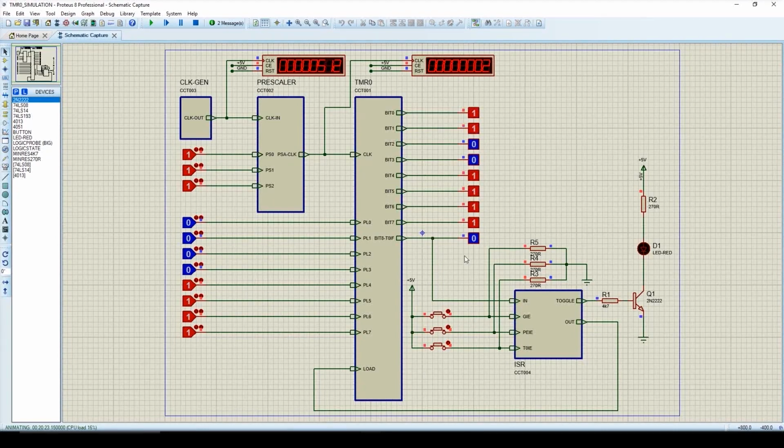We have a similar arrangement in PIC16F877A. The clock speed in PIC16F877A is 10 MHz in our case, and we'll observe the same operation in PIC16F877A, and we'll write a program to get the interrupt after every 1 millisecond.